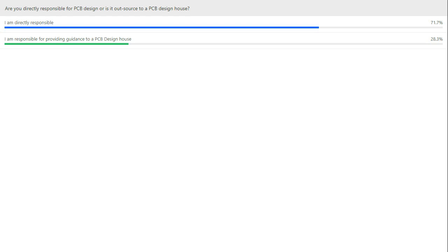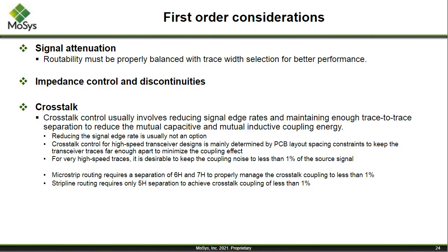So this information might be old hat to you in some ways, but it's really important to us as users to understand how this is done and what to look out for. Even as a process at MoSys, we do a lot of reviews associated with PCB layouts around the MoSys device, around the SerDes layouts and the power layouts associated with the device itself. Using some of the Allegro tools, visual inspection is really an important tool that we've used for understanding what's going on.